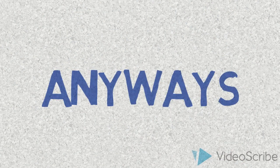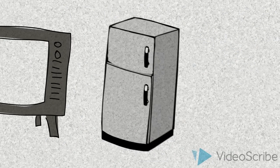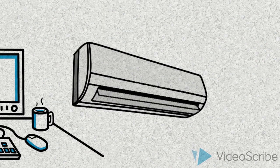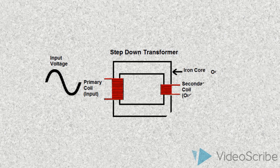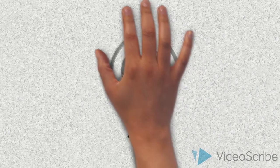Anyways, this is not the only purpose of a transformer. Transformers are also used as regulators for televisions, refrigerators, computers, air conditioners, and many more. Similar to transmission lines, in air conditioners, a step-down transformer is used to step down the voltage from line voltage to a safer and more efficient voltage for use. Step-down transformers can take 120 volts to 24 volts or 240 volts to 24 volts. There are many other combinations.